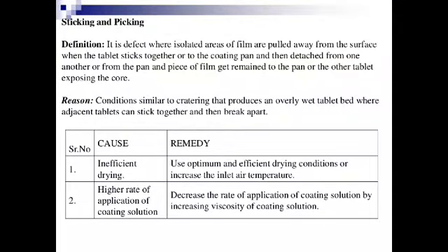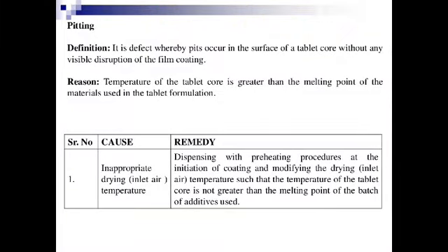The sticking and picking are also due to improper drying or an improper rate of application of the coating solution. So all this has to be optimized, otherwise it will lead to sticking and picking problems. Then pitting is the defect where pits occur on the surface of the tablet core without any visible disruption of the film coating.